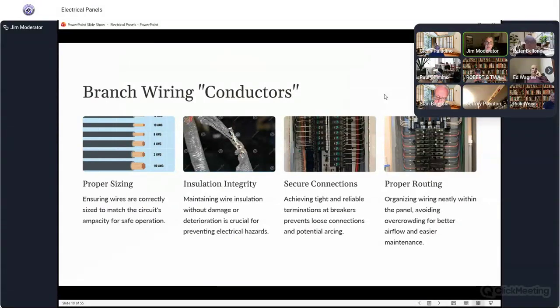The feeders are on the left side of the panel to a 100 amp breaker. So you have 100 amp service, and the size of the wire was appropriate for 100 amp service. The homeowner thought that they had 200. The buyer thought that they had 200, but they didn't. And the homeowner didn't know that, because I did that inspection and they never got it changed. She didn't upgrade. So you've got to be careful. Don't just look at the label, you've got to look at the wire size too.